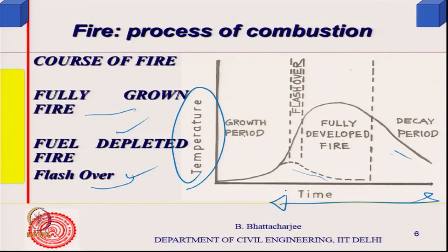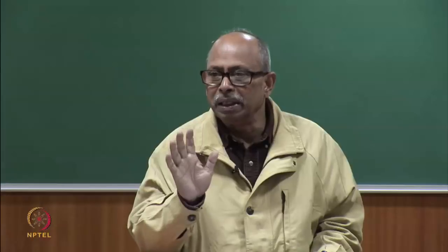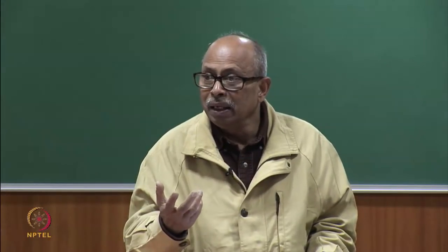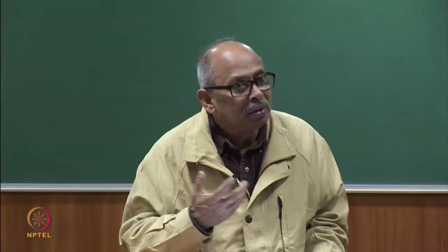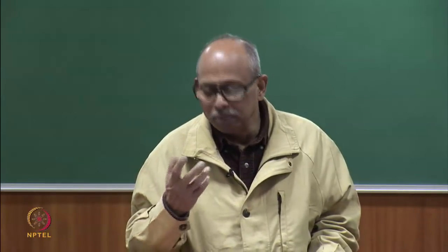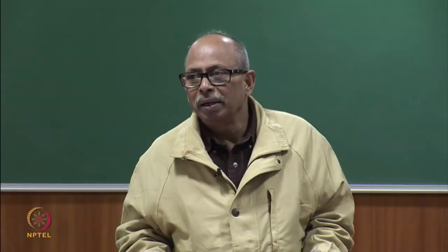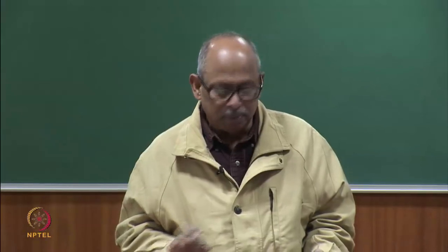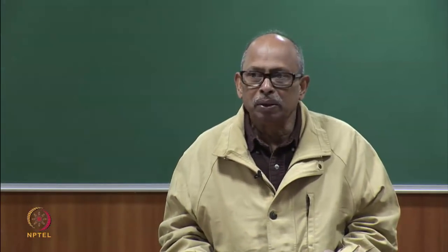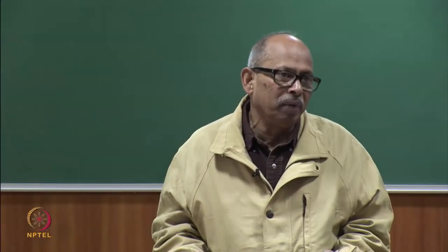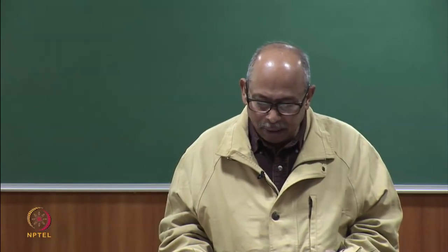Supposing I have a lot of fuel, then the steady period would be longer. I am talking of fuel density, room volume remaining the same. If you have a higher fuel density, it would require longer time to burn out. So temperature and time, these are the two issues. Fires are defined by the time temperature curve. We will come back to this again.